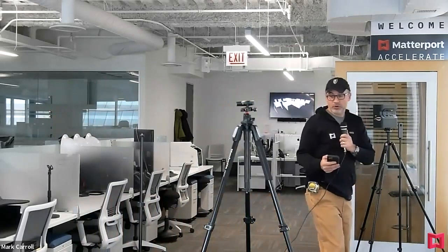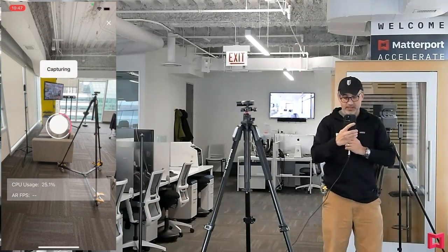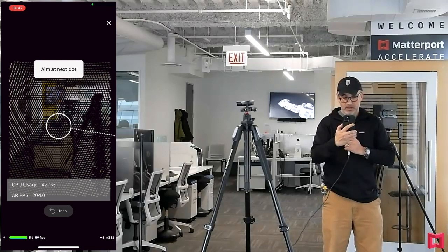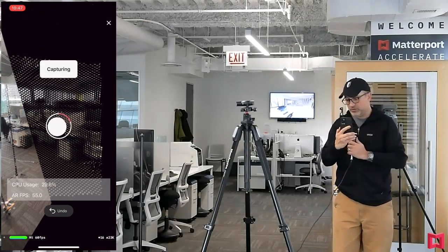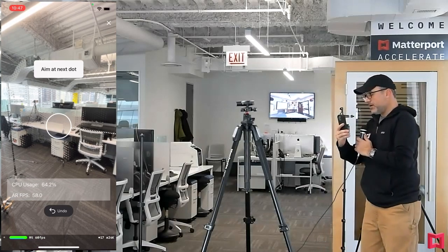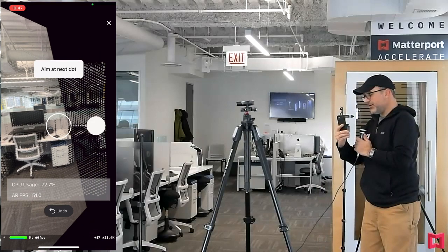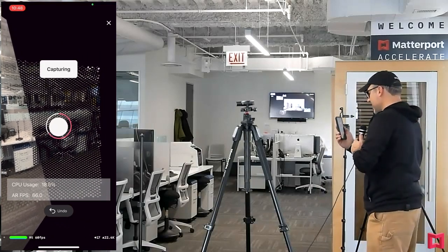So I can see on the screen that that first position has landed. So what I'll do is I'll count 1, 2, 3 paces away. I think 3 paces is a good first distance away. And I'll press it again on my screen. And it right away goes into the Capture app's version of this LiDAR output that has those dots on the screen. These don't pop up when you're using the Matterport Capture app that does not include LiDAR.